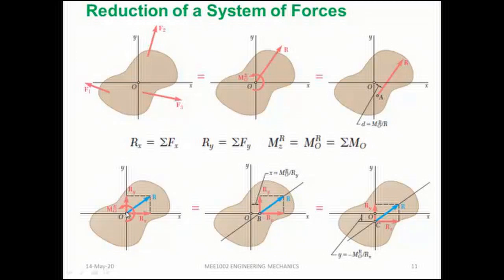Similarly, this can be moved in Y, so that you can remove this moment, or the couple. Now we have to find the Y intercept, where at Y these components are acting such that the net effect is not changed. That is the intercept point. This is the X point where you put the resultant force, so that the net effect is unchanged. All these are equal. In any form, you can write and solve the problems.